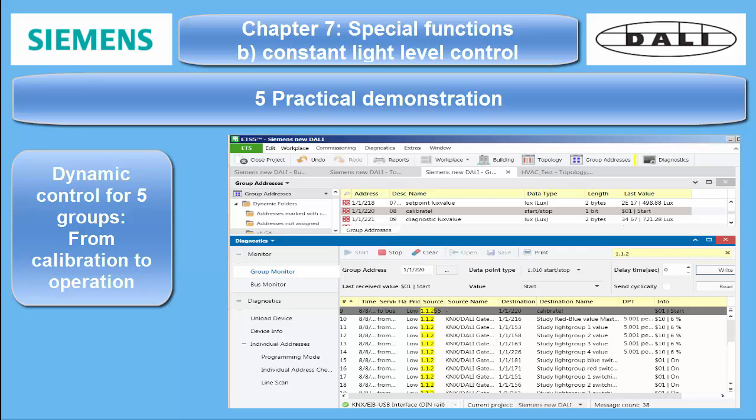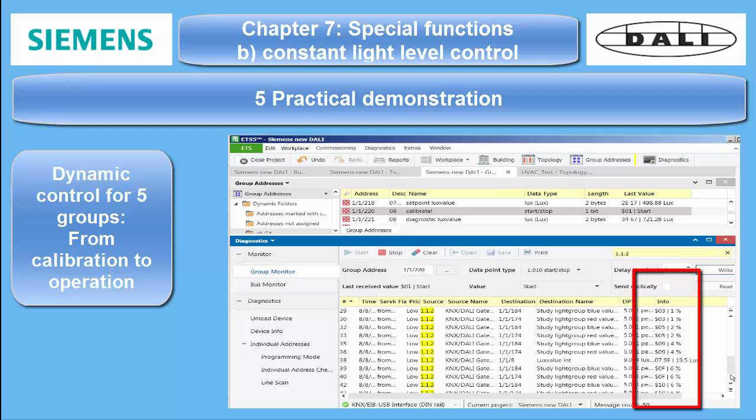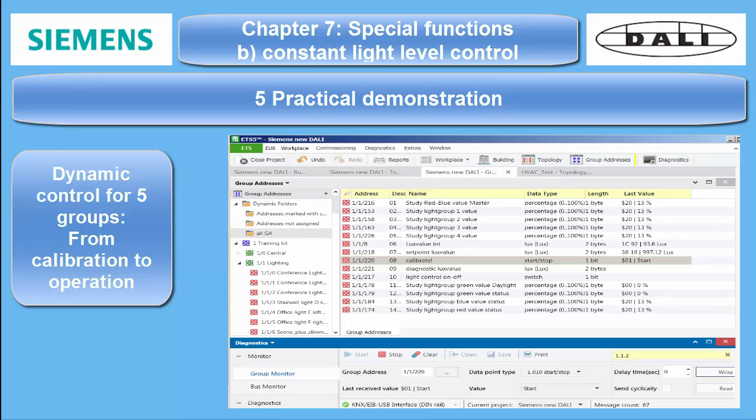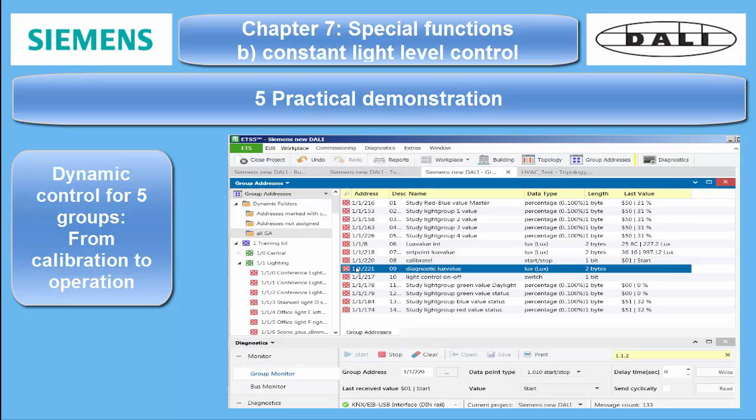You can see that it starts with switching on telegrams to all lighting groups. Only then it can send the 16 dimming values in ascending order. The values are easy in hex reading, starting with 10, always counting up by further 10 hex until reaching FF. Since the current values for the group addresses are also sent, I show them in the column Last Value of the group window. Finally, all values will be sent out one by one through the object diagnostic value.